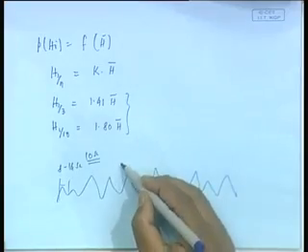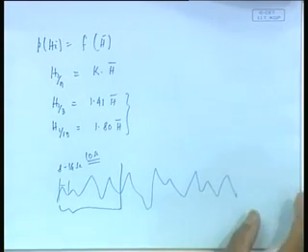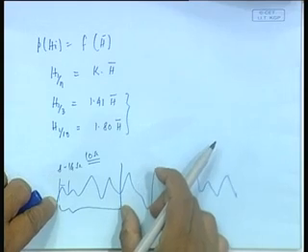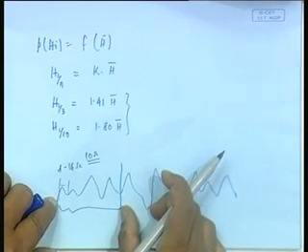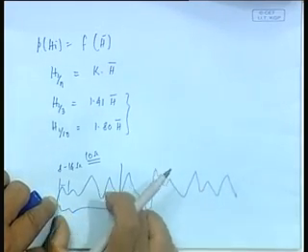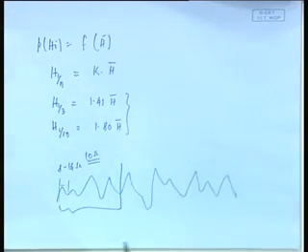So what often people do is that you cluster these things into some time intervals. I am talking from the point of view of data processing. You cluster this for, let us say, every 1 minute, then average this value and take that as a wave height. So you have then a reasonable number of data.